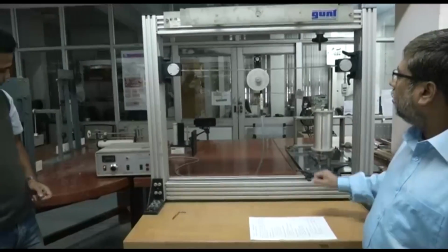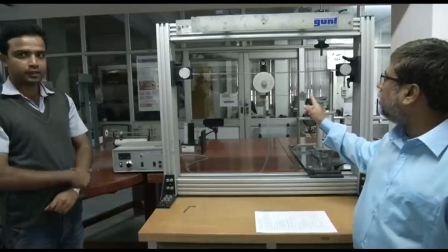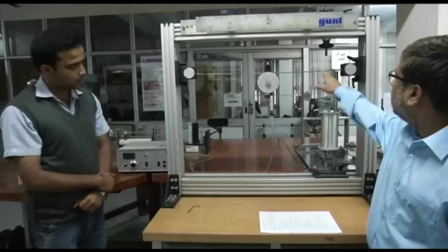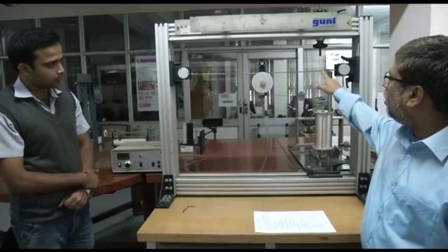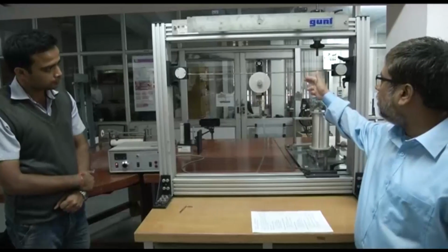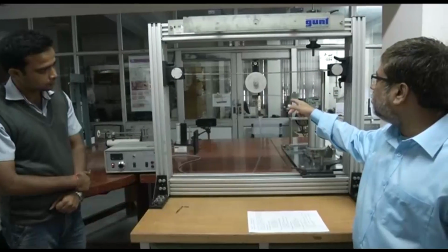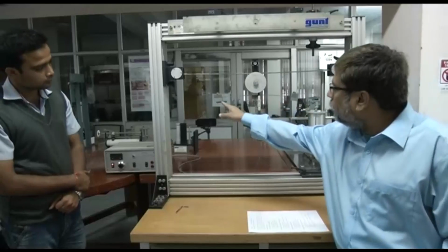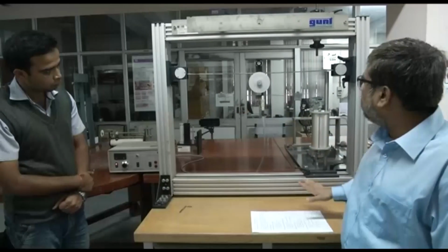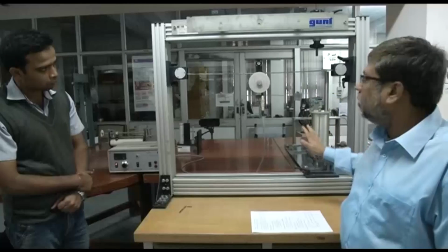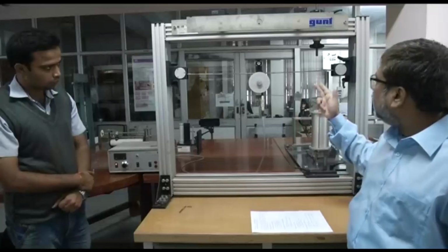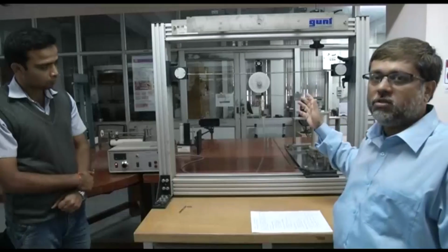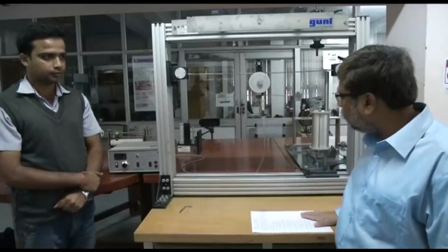Yeah, we are having 6.98. So we are at 6.98 Hz, and as you can see, there is no vibration apparent in this beam. Why? Because the entire energy from the primary beam has been transferred to the secondary, and the secondary beam with these masses is vibrating while the primary one is steady. This is one strategy of vibration control which we will teach in much more detail in this course, and it is known as tuned mass damper based vibration control.